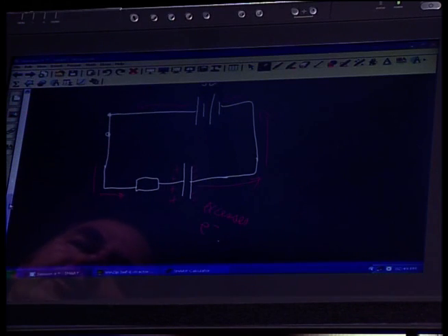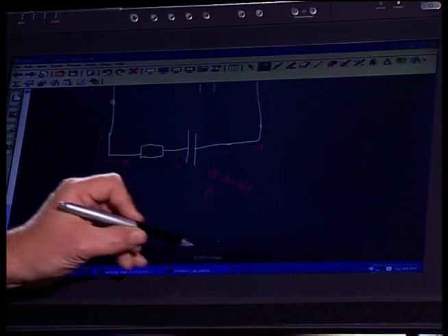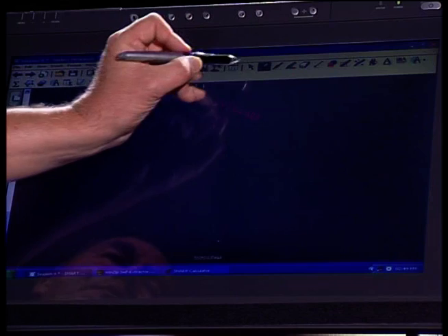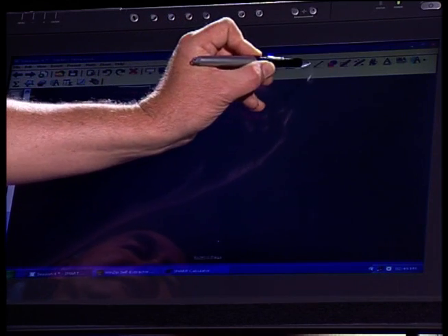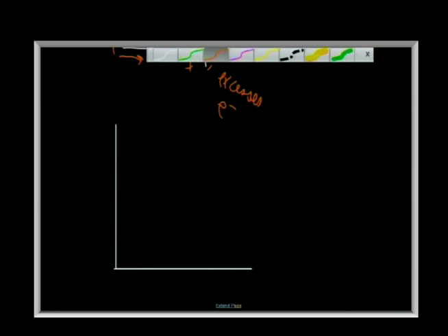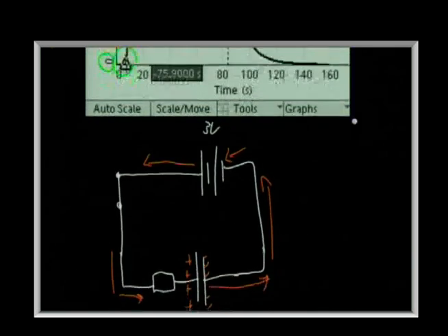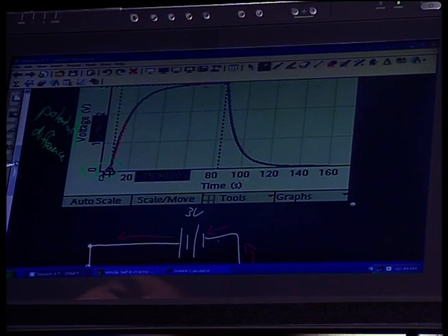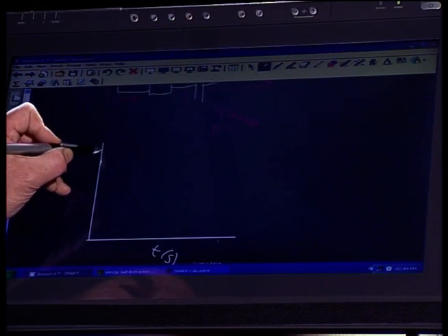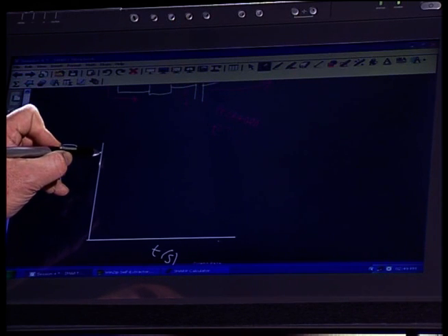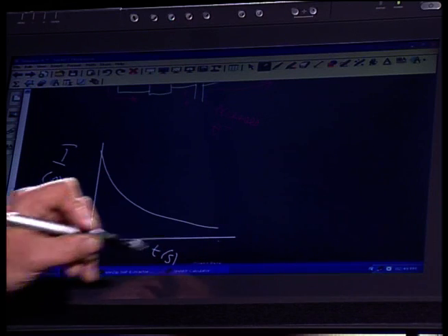What's the flow of current? What's the flow of charge going to be? So what's our current graph going to be? So what you should recognize, initially it's easy. So if we had to draw the same graph, just sketch it for a certain time while it's charging, and we're going to say this is current measured in amps, and we're going to measure time measured in seconds. What's going to happen? Look what's happened to the potential difference. It increased. What do you think happens to the current? Well, it's going to start high initially, wants to move the charges, and it's going to decrease, something like that.